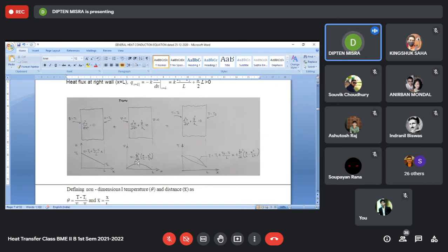And what is there on the denominator? The unit of K, you should try to remember this, is watt per meter Kelvin. So on the numerator we have watt per meter, and on the denominator you have watt per meter Kelvin. So effectively it becomes Kelvin. So this also represents a temperature, and this is a very standard way to represent some kind of temperature. Not a temperature, it becomes a temperature difference type of thing.